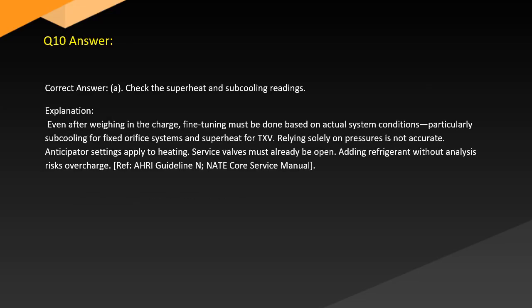Answer. Correct answer: A. Check the superheat and subcooling readings. Explanation. Even after weighing in the charge, fine-tuning must be done based on actual system conditions, particularly subcooling for fixed orifice systems and superheat for TXV systems. Relying solely on pressures is not accurate.